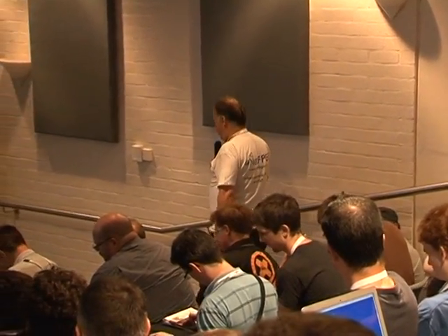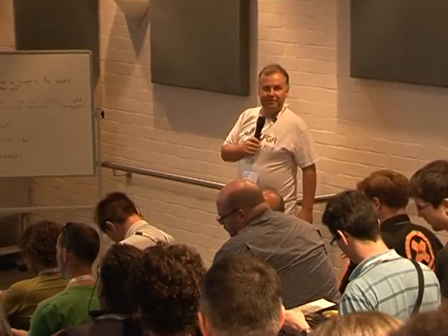So I haven't thought about channel bonding at all. The intention is to have one USB port per Tegra CPU. Haven't actually considered whether you need more bandwidth. But as far as I know, the Tegra CPU only has a single USB controller, so bonding the USB wouldn't get you anything. If you could bond it with some other interface that's available, you might get some extra. But the Tegra 2 itself only has a single USB channel.